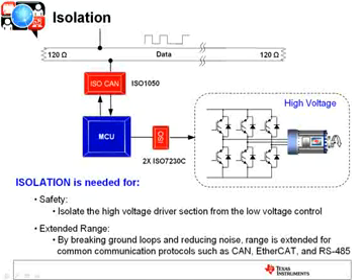In addition to the safety aspect, the very noisy industrial environments, as these motors become more and more networked, and you need to control them remotely, they're using CAN buses, EtherCAT, RS-485, and these buses in these noisy environments have range limitations. You can greatly extend that range or lessen the bit error, improve the performance of those buses by putting some isolation in between the controller and the bus itself.